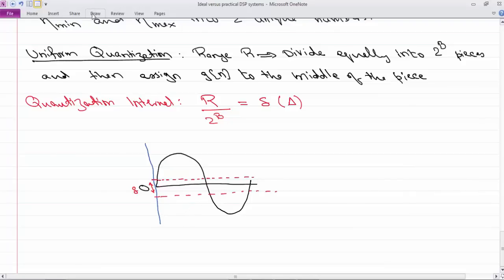So if I were to, mathematically speaking, sample something here, this is my value. My value is not 0. But because I have a quantizer, an ADC, when it measures any value in this range, it's going to assign that value 0. So if I actually look at what value my ADC is producing at this point, the ADC will produce this 0 value instead of a non-zero value.